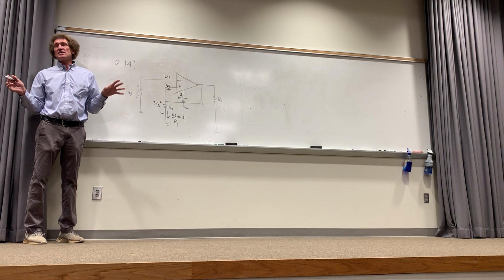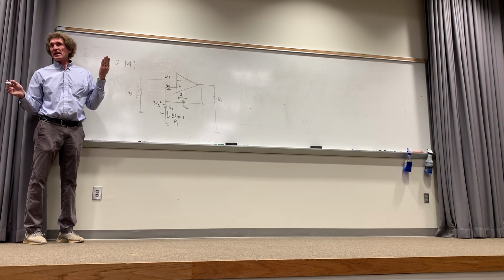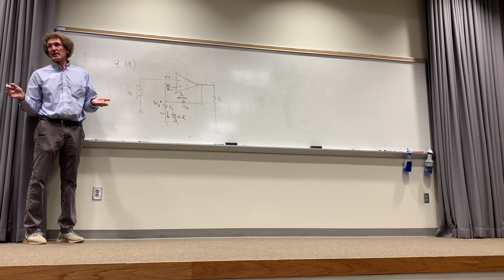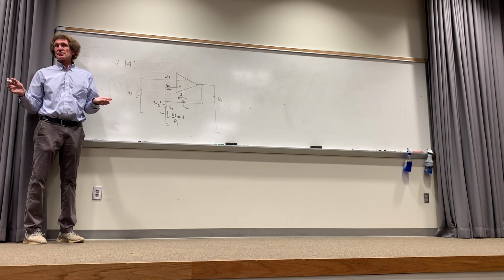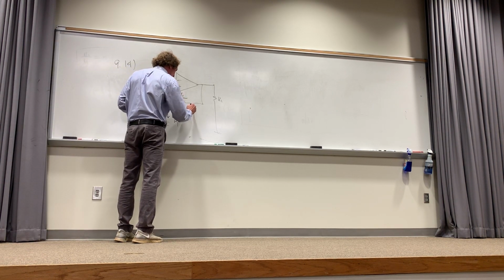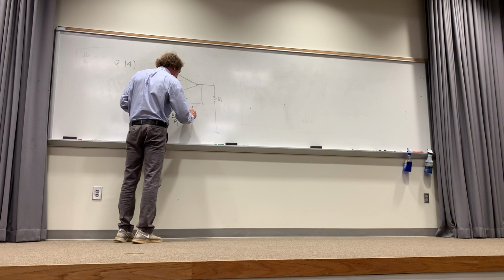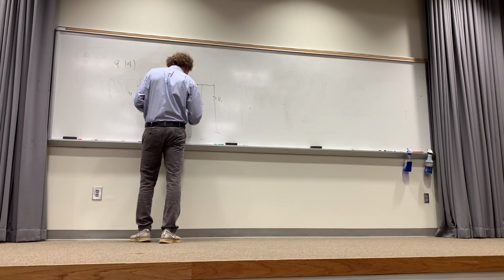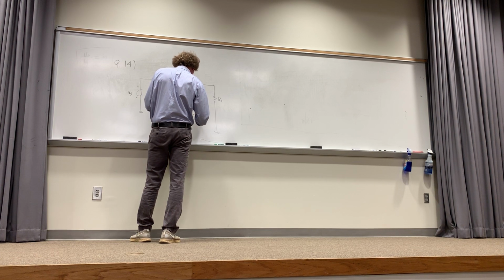Matter of fact, most engineers are, by their very nature, deductive reasoning people. You think through a problem based on the premises. What is true? And then you reason your way through it. So here, I know that's the current through there, and I know the voltage here, V2, which is going to be plus to minus, V2 right there is simply I1 times R2.